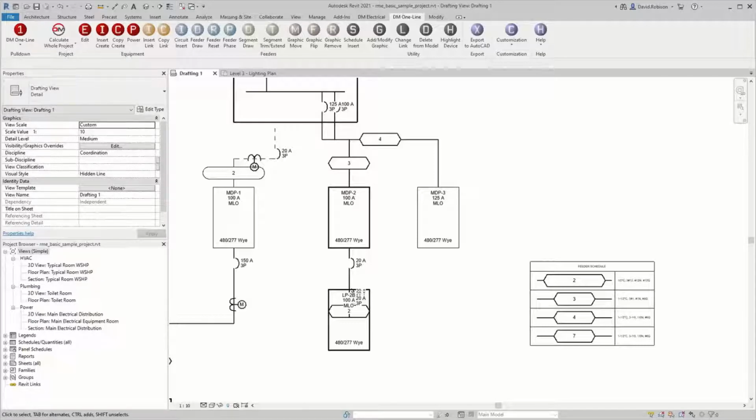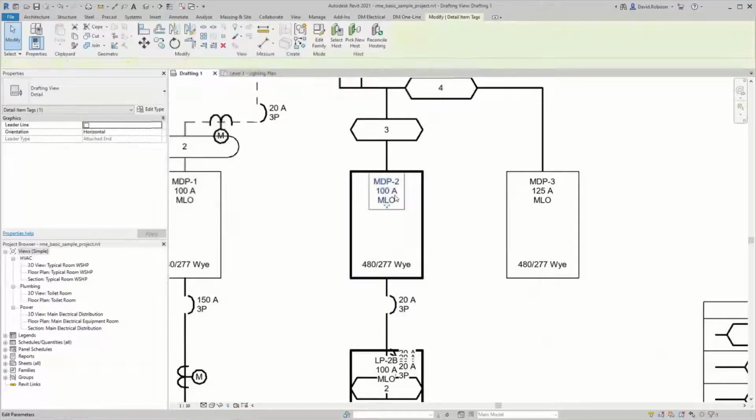What you'll want to do in that case is on the demo, basically the one that doesn't match the actual model, go into the demo and erase that label and put in just standard Revit text to label that size. Yeah, and this is kind of a shortcoming of Revit, is that it doesn't really handle phasing, particularly of electrical equipment, very, very well. They attempt some phasing, and I think it probably works better on the architectural side, but electrical, it struggles. So just go into the existing and modify it to just label it manually.